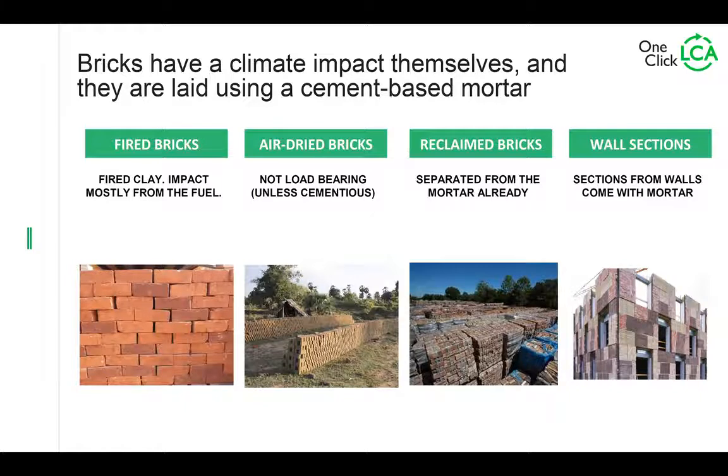There's also air-dried bricks, not big in Europe, but a very interesting approach in some African countries, also like other hot temperature countries where you don't have to always build tall, and where the cost of firing bricks may limit use. So air-dried bricks are also used in a number of regions. They are not load-bearing. Sometimes cement is added to them, and of course that pretty much destroys the equation. So it basically makes them clay-based concrete blocks. So they are then environmentally undesirable products.